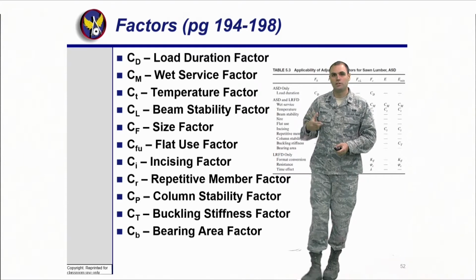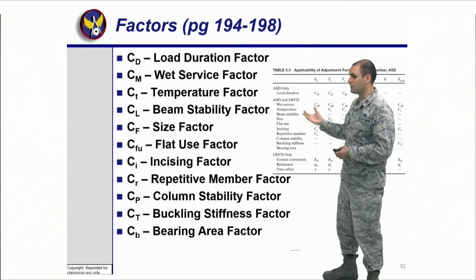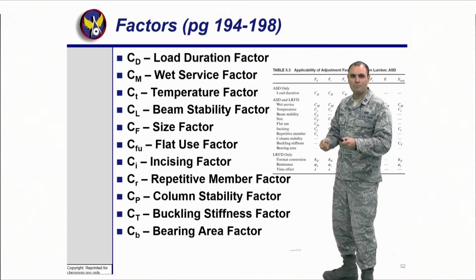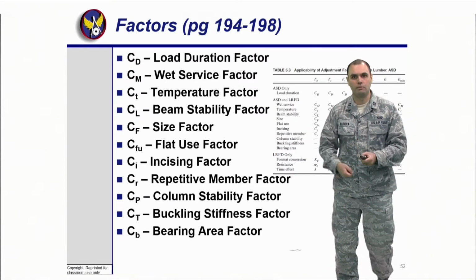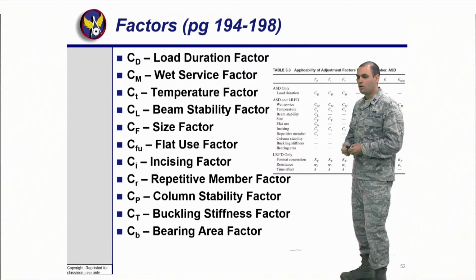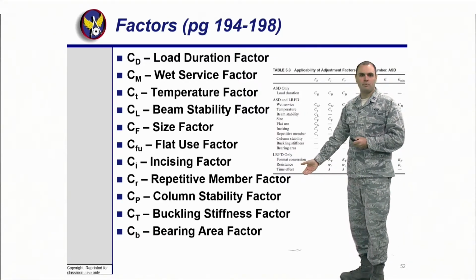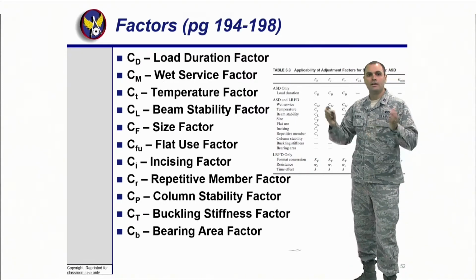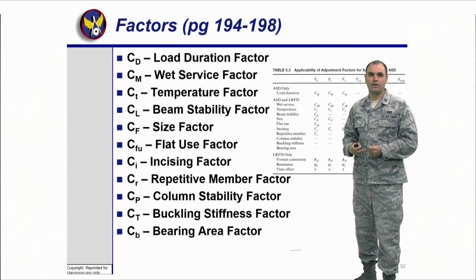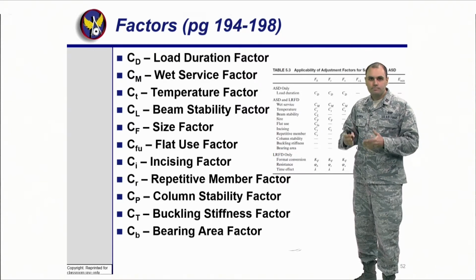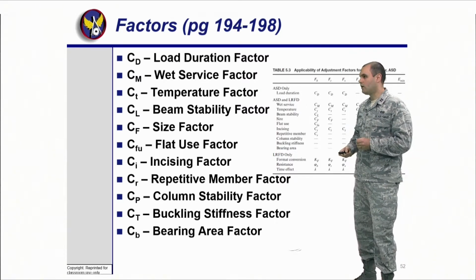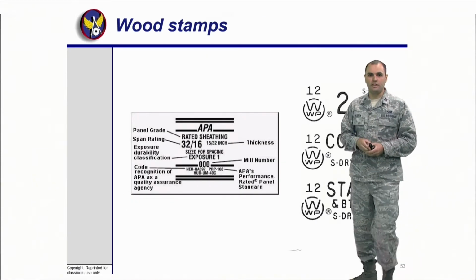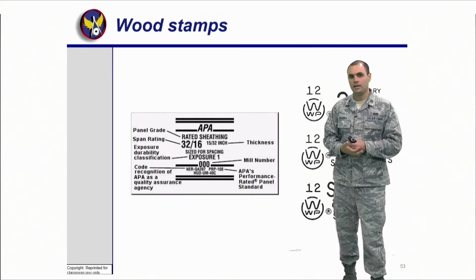Again, you only use the ones that you need for your design. This is another reason why wood is heavily used, because you can kind of manipulate. Well, I'm really using it for wet use only, so I'm going to decrease this. We're done. Or there's a lot of these members, so there's a repetitive member factor. I'm actually going to increase my strength a little bit, because if my stud or something fails, I have another one that can take over. So just to kind of get you going, it gives a lot of flexibility to those out there. Another thing is wood needs to be stamped, all right?